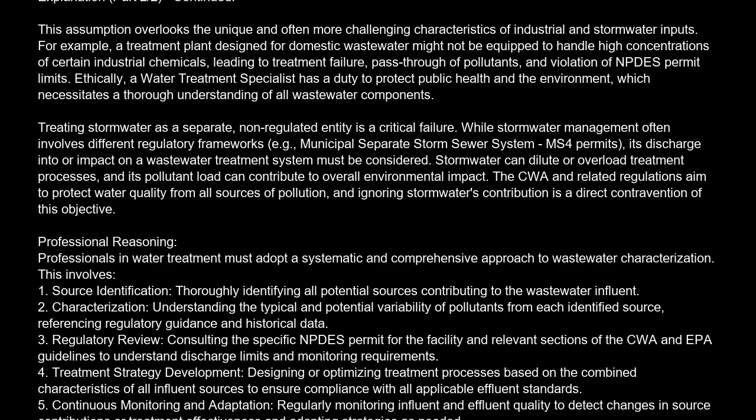Professional reasoning. Professionals in water treatment must adopt a systematic and comprehensive approach to wastewater characterization. This involves: 1. Source identification, thoroughly identifying all potential sources contributing to the wastewater influent. 2. Characterization, understanding the typical and potential variability of pollutants from each identified source, referencing regulatory guidance and historical data. 3. Regulatory review, consulting the specific NPDES permit for the facility and relevant sections of the CWA and EPA guidelines to understand discharge limits and monitoring requirements.